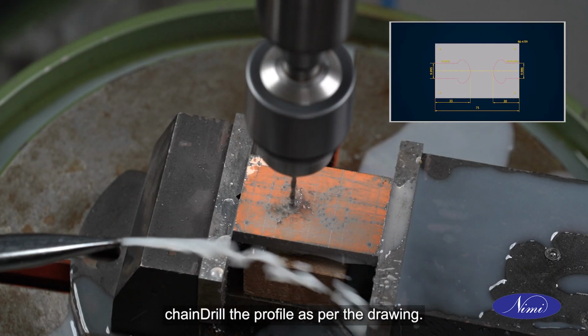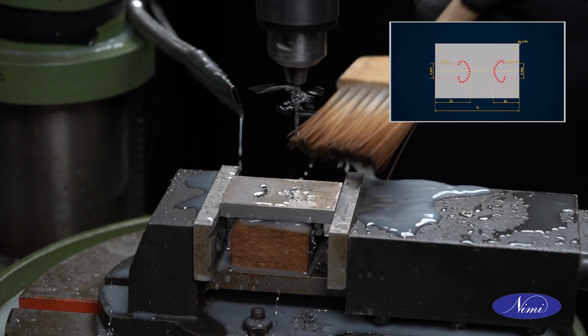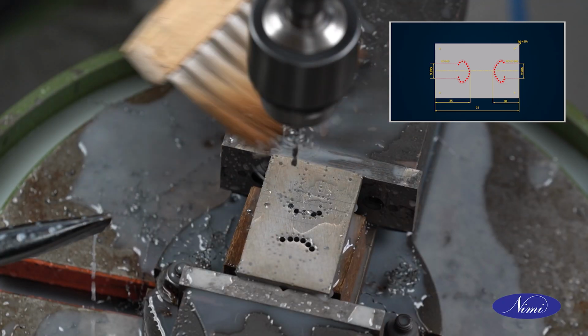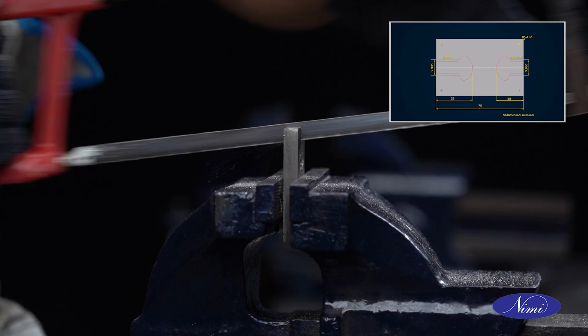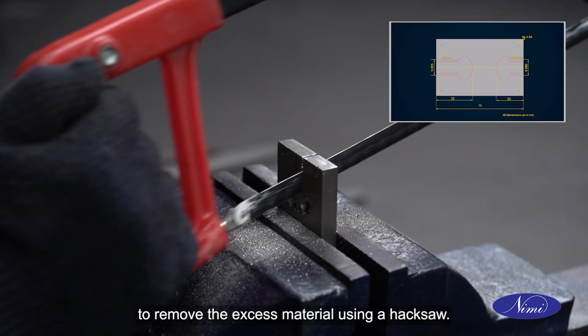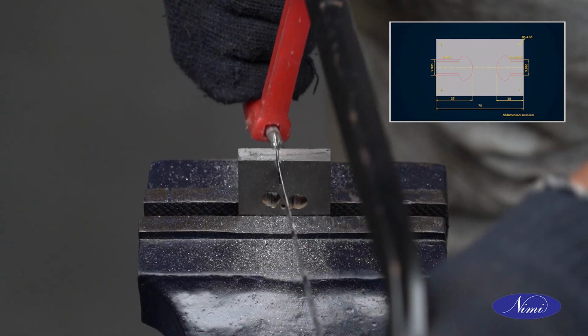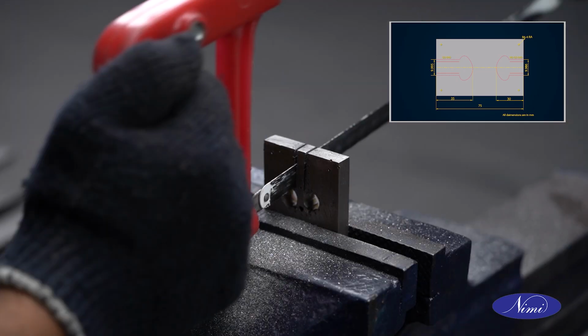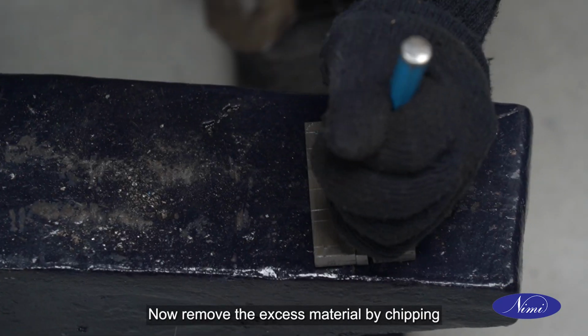Chain drill the profile as per the drawing. Perform sawing operation to remove the excess material using a hacksaw. Now remove the excess material by chipping.